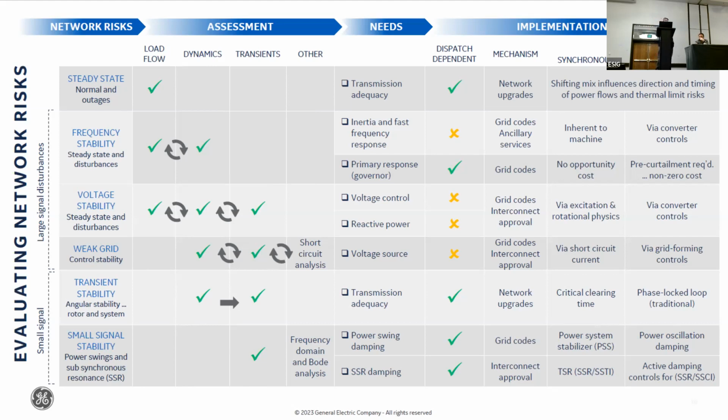And the hard part is you run the production cost model, you get the dispatch, and there's another piece about deciding which hour. And I think one of the other panelists did a great job in showing that type of analysis. But once you settle on an hour that you're going to analyze, whether it's a high renewable hour or a high peak load, you have to then transport the dispatch decisions from the production cost model into the power flow analysis. And that's a bit of the model integration that requires a bit of time and effort.